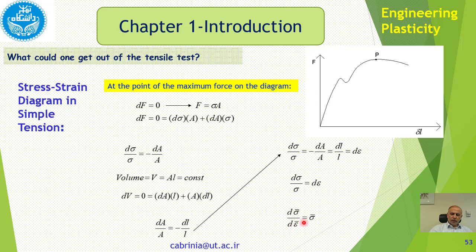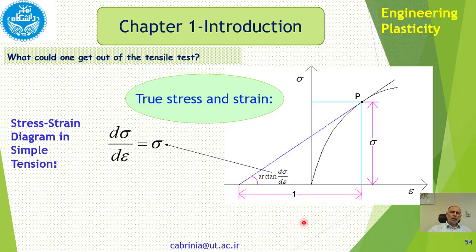We'll come back to this later on. We can show that for a stress-strain curve, that is F over A, that's delta L over L, or ln L over L0. And what we can see here is that this is a true stress-strain curve, and where is the instability? We don't know which point it is, but from this we can find out.